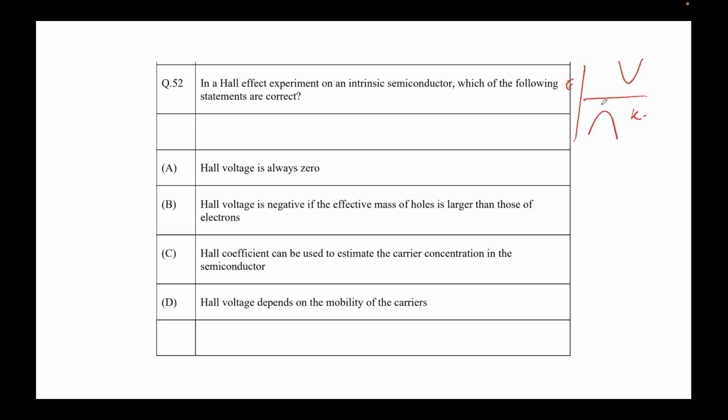So this is your silicon, this is your valence band, conduction band. Let's say an electron wants to go from here to here. It will go through this path, so it will need this much energy, which will be provided by a photon. A photon has energy h nu, correct, and the momentum change will be provided by a phonon. Every phonon has a certain momentum. We'll see about phonons in solid state physics; I was not going in depth because there's a good phonon concept there.